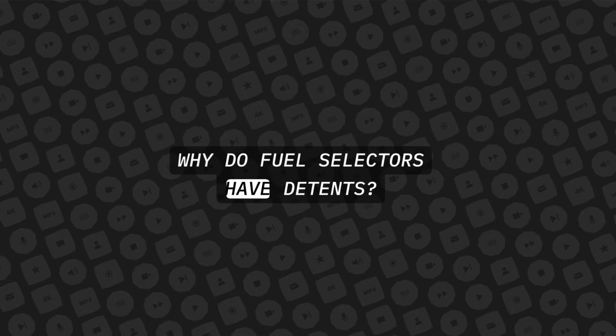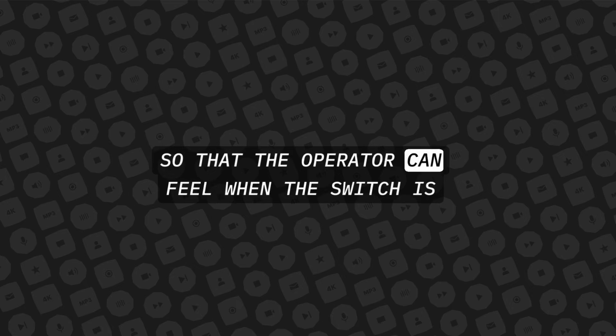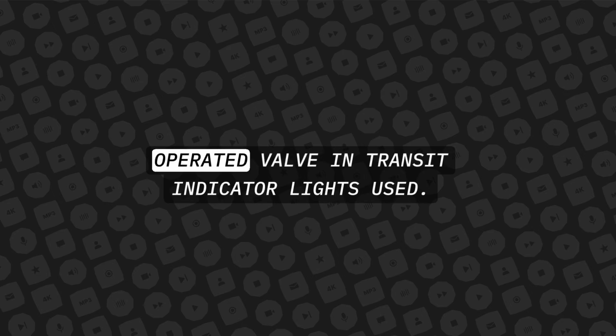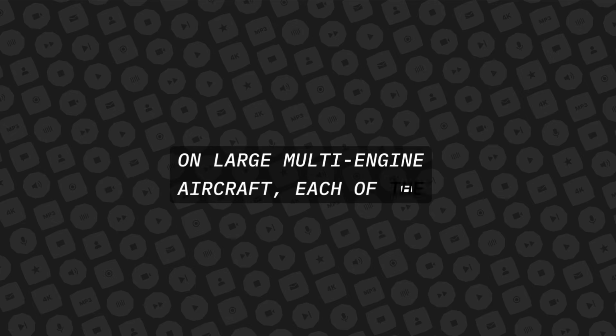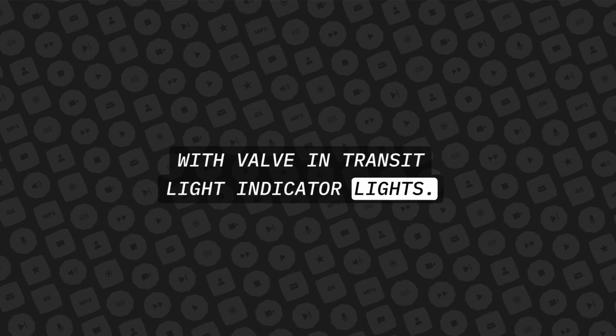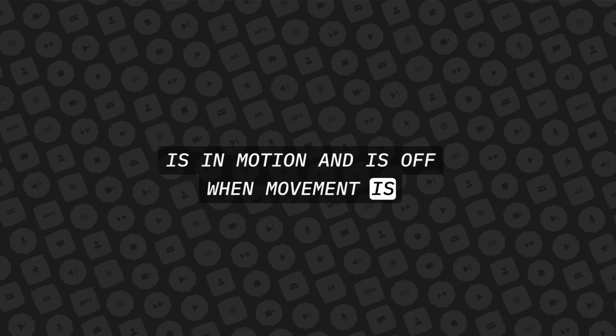Why do fuel selectors have detents? To lock the switch into the selected position, and so that the operator can feel when the switch is in a specific position. Where are electrically operated valve in transit indicator lights used? On large multi-engine aircraft, each of the fuel cross-feed and line valves may be provided with valve-in-transit indicator lights. The light is on only during the time the valve is in motion and is off when movement is complete.